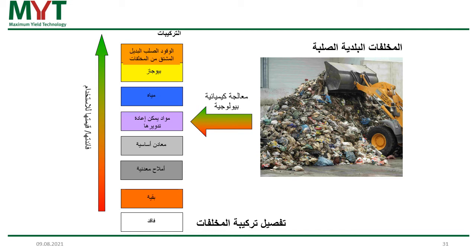we do not want to put in any category here, because, for example, there are some materials which we better landfill than transforming it to RDF, because burning or firing this material would cause very harmful emissions, which are difficult and expensive to clean in the flue gas cleaning system. So sometimes it's better to decide to put a certain piece or a material on a landfill site instead of incinerating it. And this is why you also need to know your waste and where it comes from. That makes this decision much easier.